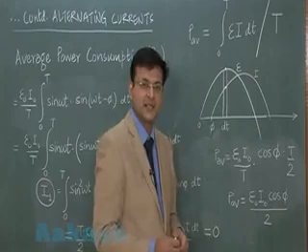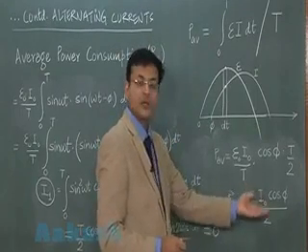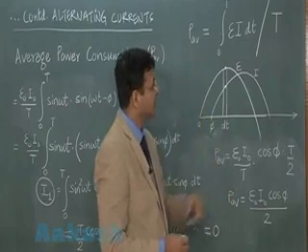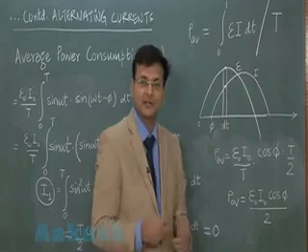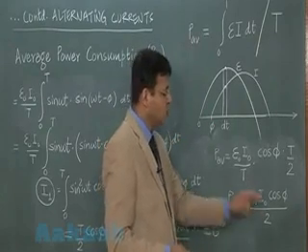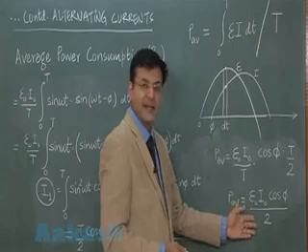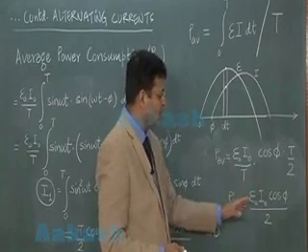You understand? This is the kind of derivation we had so long as the average power consumption in an alternating current circuit is concerned. Now you will have to have several discussions on this average power of consumption in alternating current circuit, how it can be manipulated for our convenience. Here the factor 2 which you are getting, that can be divided as root 2 multiplied by root 2, and it can be allocated to these E naught and I naught.